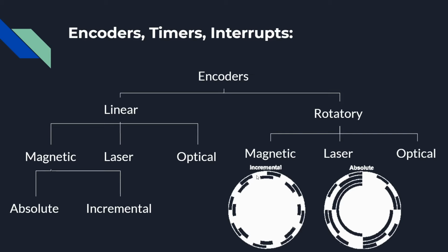If it is rotating clockwise, always the sensor that's reading the outer peripheral laser is receiving it first. That means the disk is rotating, the motor is rotating clockwise. If this one is reading it first, it would mean that it's rotating counterclockwise.